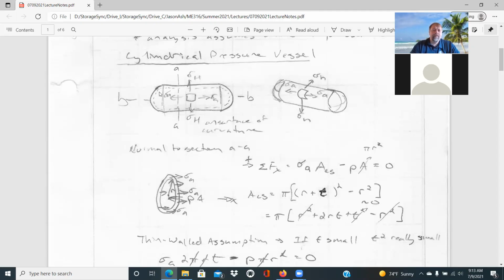And even though, say you have a hemispherical cap here, the pressure always acts normal to that. So it's going to be acting at an angle, but it's also acting at an angle down here. And so those vertical components cancel one another out between the top and bottom of that hemispherical cap. And so the net effect is still that projected area of the pressure times the area of a circle that it's acting against. And that simplifies things considerably, realizing that a lot of those forces cancel one another out.